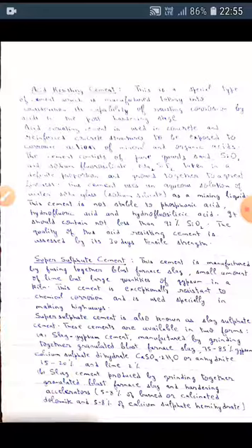organic acids. The cement consists of pure quartz sand, SiO2, and sodium fluorosilicate, Na2SiF6. They are taken in definite proportions and then ground together to a great fineness. The two constituents of the cement can be ground individually, then the two powders may be mixed intimately. This cement uses an aqueous solution of water soda glass, that is sodium silicate, as a mixing liquid. Concrete with such a cement as a binder turns in air into a strong stone material.